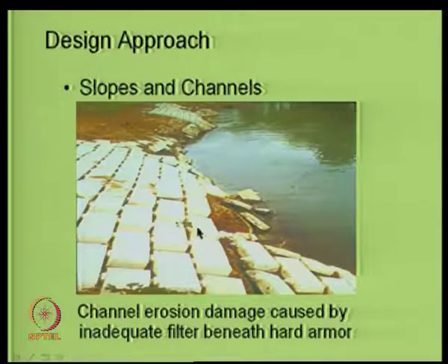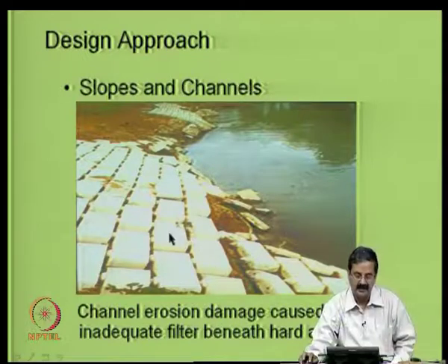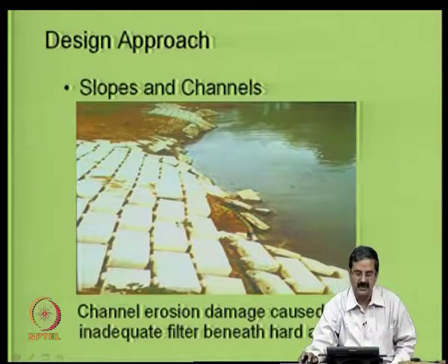The design was not good. And maybe there is no connection between the two panels, and if one panel comes out, all the rest of the materials come out. The design, the choice of the system itself, one should be very careful. Suppose there is a lot of subsurface flow that comes, and if you don't design for subsurface flow and see that the subsurface flow neatly comes out, there are many issues.